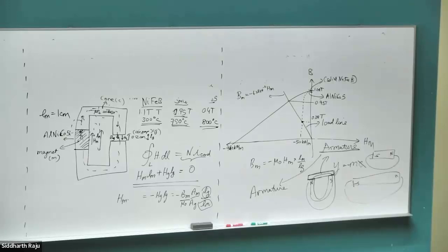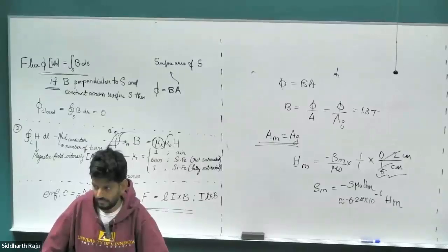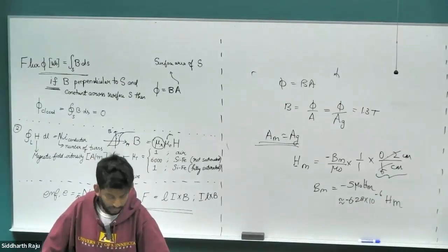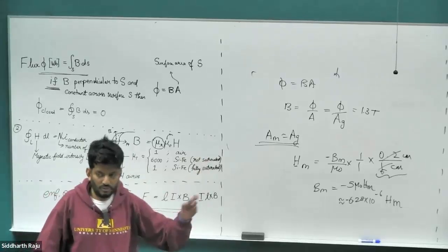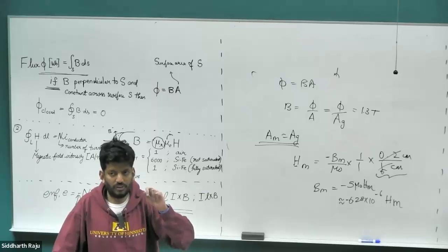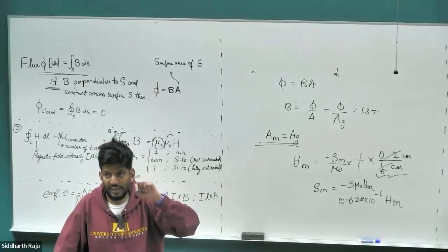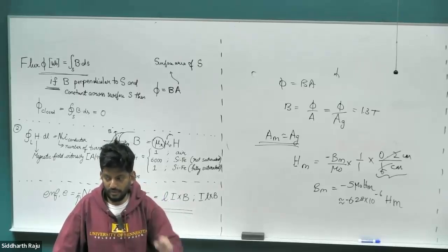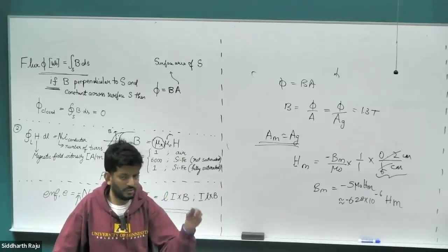Yep. You have to worry about the decrease in field strength in motors? Is that something you have to model or ever care about? It is. So that's the reason in a motor we want to make the air gap as small as possible, right? As tiny as possible. The higher powered motors would typically have a very tiny air gap. 0.5 millimeter is a good number. For smaller power, you can go with a larger air gap.